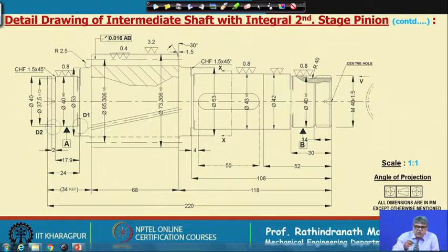For that we need a center hole. There are special tools by which we can make a center hole. Even this piece can be machined in some other very rough cutting machines, say 225 millimeter long with center, or maybe 222 or 223 with this center hole. We can take this piece and then put it on another lathe for final machining.